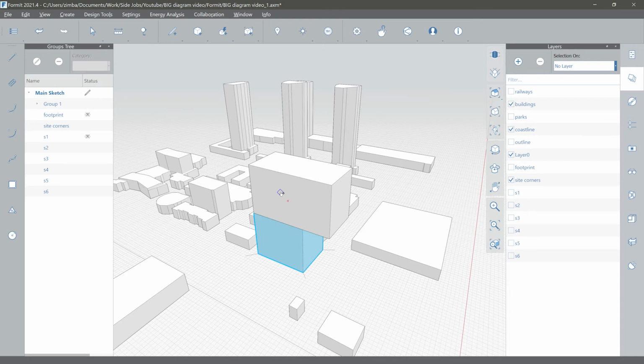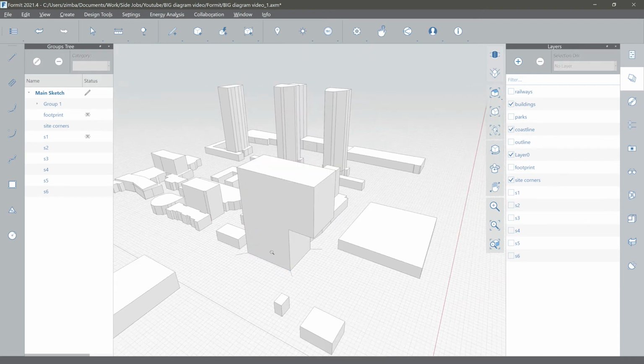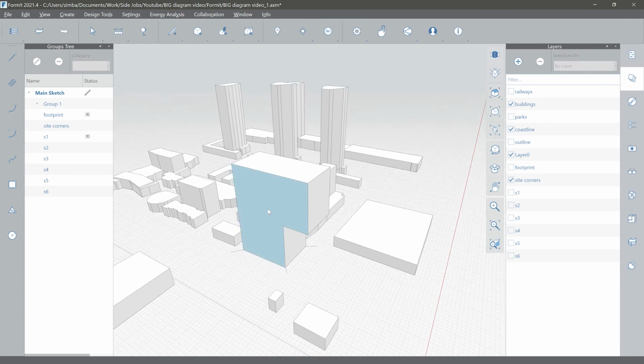So we'll double click, hold on Control, and go to the advanced geometry tools, and we'll just do join geometry. And now we'll press OK, and now that line goes away. So this will be the last sequence. So we can group this. S7. And then add a layer, and we can just add it to layer 1.